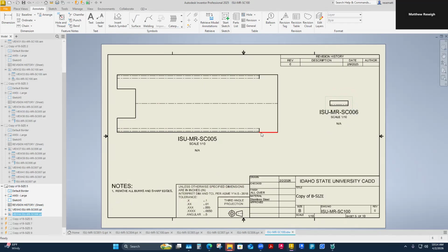And I've seen a whole nest be cut at the wrong scale, which makes you have a really sick feeling in your gut, knowing you just cut a whole sheet of wrong parts and the sheet was several $1,000s or something. It's a simple mistake that is unfortunate, but like I said, new equipment doesn't seem to have that interpretation issue on scaling. It'll just accept it as a one-to-one.